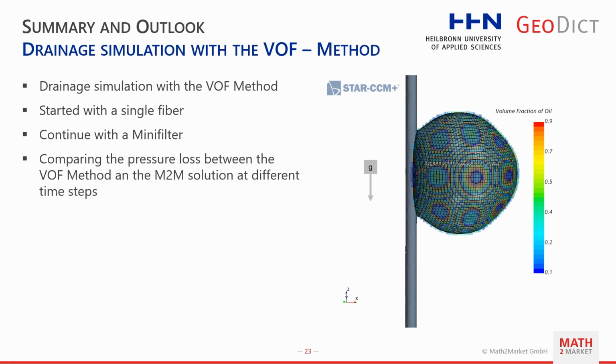This means what will happen if the oil filter is saturated, how does the oil leave this filter again? Because in a real-world filter this for sure happens. For example, the oil is just running down due to gravity, and this is one step that is still missing in our simulations.